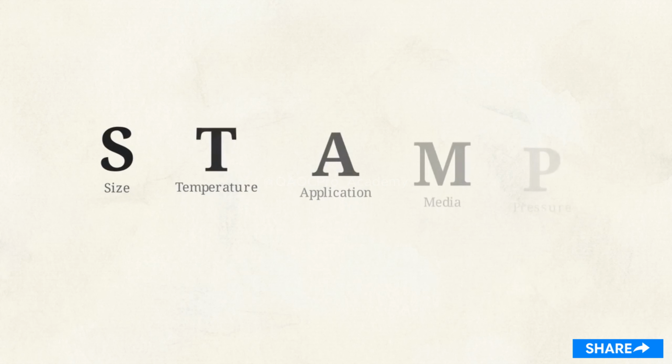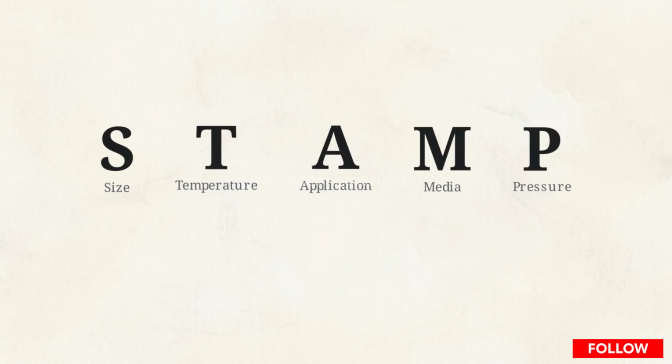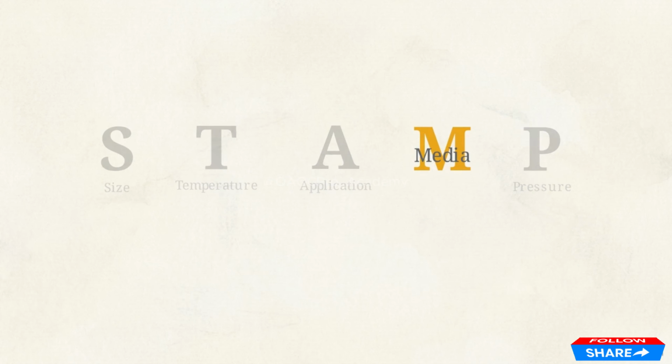This is the STAMP framework. It stands for size, temperature, application, media, and pressure. It is the mandatory checklist you need to run through before evaluating any flange connection.